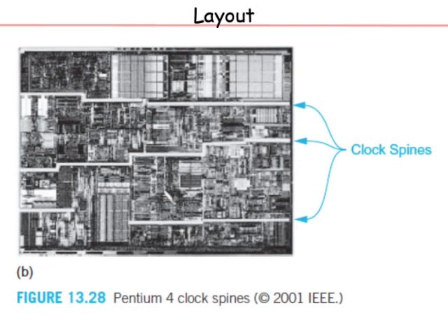You can do clock gating. We studied clock gating in one of the earlier classes. So you can shut off clocks. Global clock has to keep on happening. Maybe you shut off the global clock when the whole chip doesn't need to work by shutting off the PLL or doing something. But there are also other techniques which unfortunately we can't go into due to shortage of time, but people have explored various other techniques to reduce power consumption in the global clock distribution.